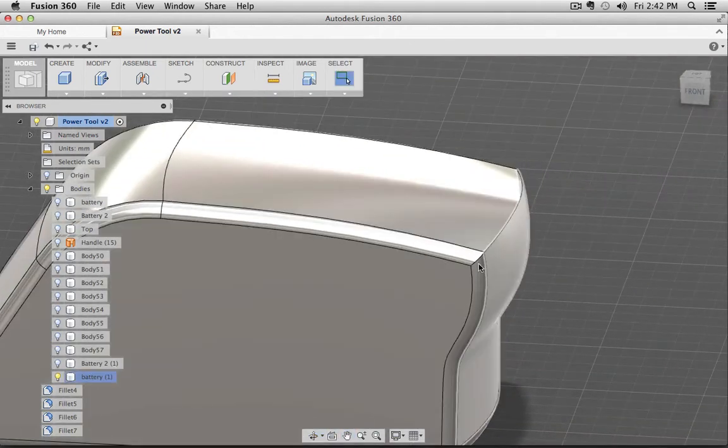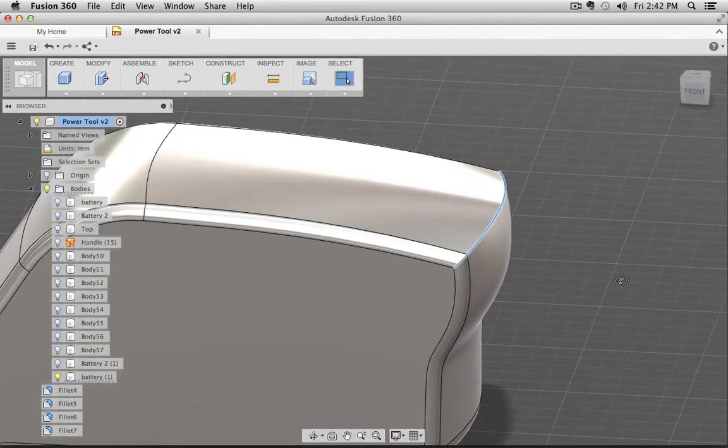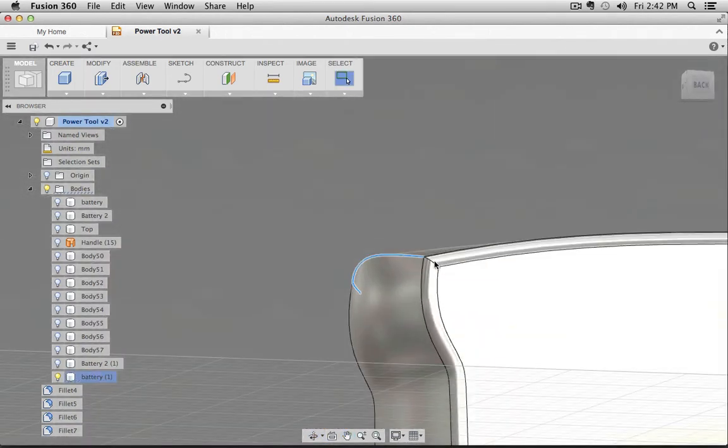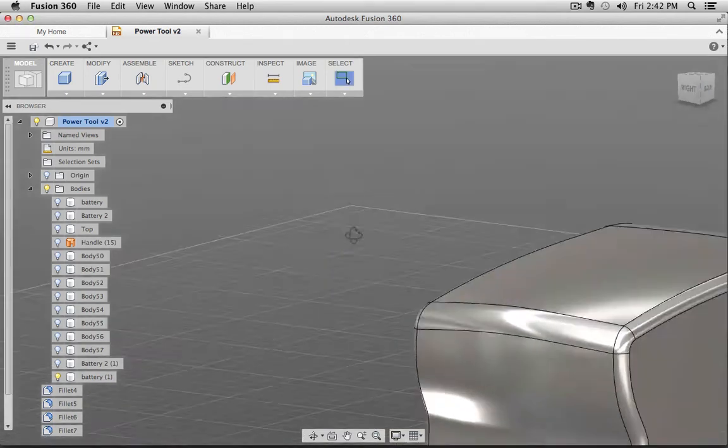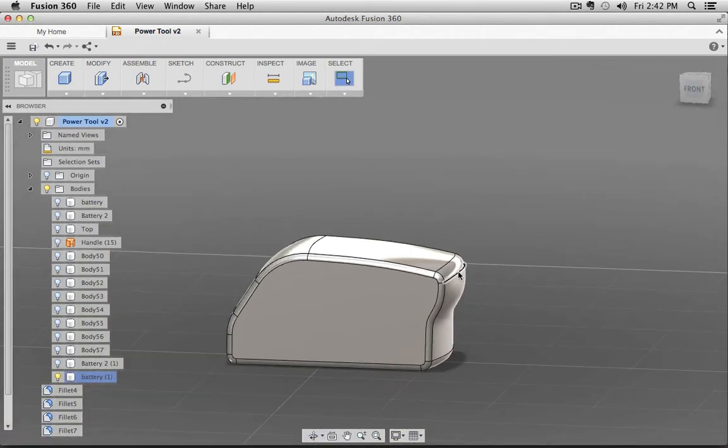And up here, this edge I did not round, so you see I end up with an interesting edge rounding. Looks like a sharp crease here. But I can also select those edges and then fillet, round them and see maybe how much I need. Maybe 6 millimeters. Okay, looks good. So you see that you have different edges, and in which order you round them can create certain results or enables you to modify them in certain ways.